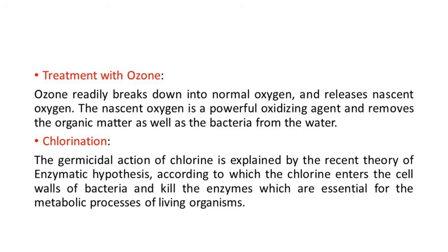The only danger in this treatment is that it needs a correct dose to get the best result. Suppose the dosage is less than required, it fails to disinfect the water. Suppose your water requires 2 ppm or 2 mg per liter of chlorine, but you add only 1 ppm or only 1 mg per liter of water, it fails to disinfect it completely.